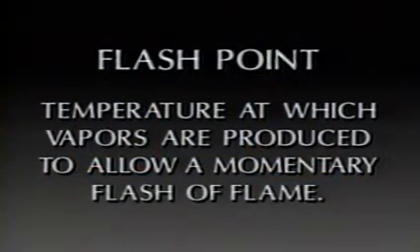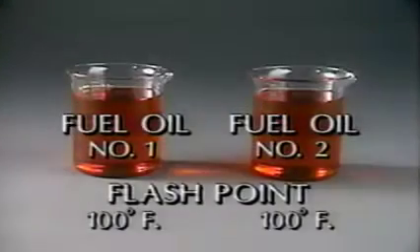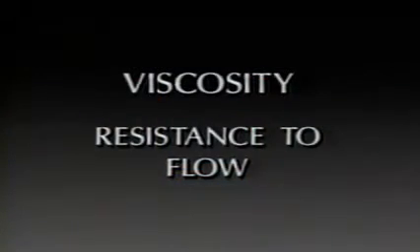Second is flash point, or the temperature at which vapors are produced to allow a momentary flash of flame. Both number 1 and number 2 fuel oils have a 100 degree Fahrenheit minimum flash point. When storing oil in hot weather or hot locations, remember that the flash point becomes an important safety consideration. Viscosity is the measure of oil's resistance to flow.